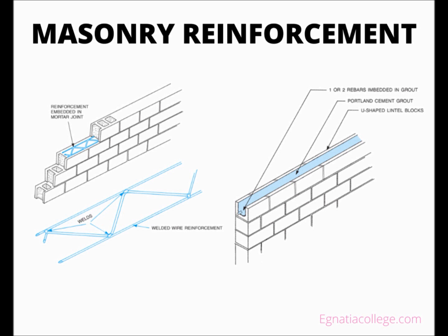The strength of a masonry wall can be increased considerably by the use of bond beams. A bond beam is made by placing a course of U-shaped masonry units at the top of the wall. Reinforcing steel is placed in the channel formed by the U-shape. Then the channel is filled with grout. The result is a reinforced beam at the top of the wall.